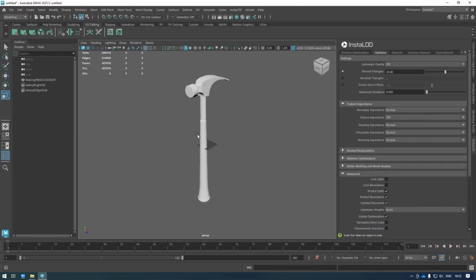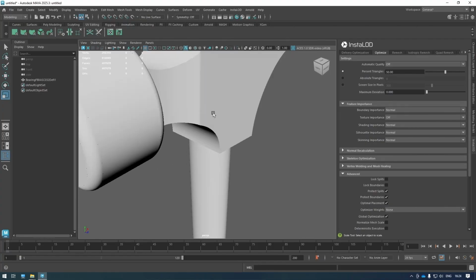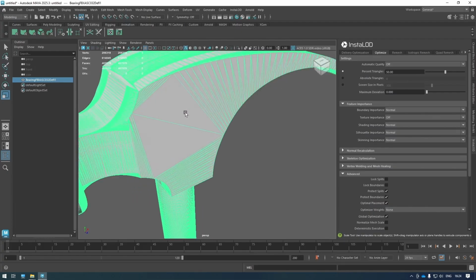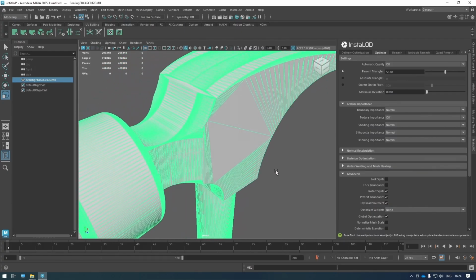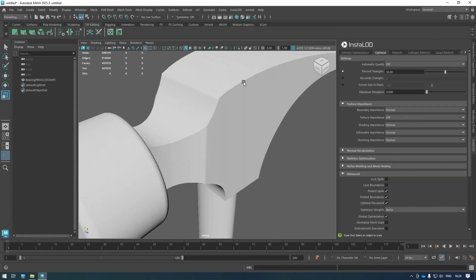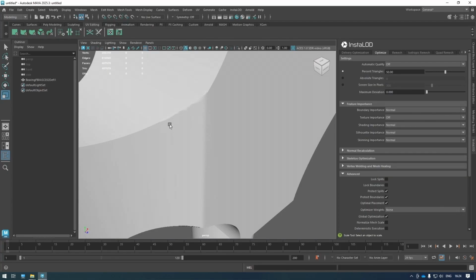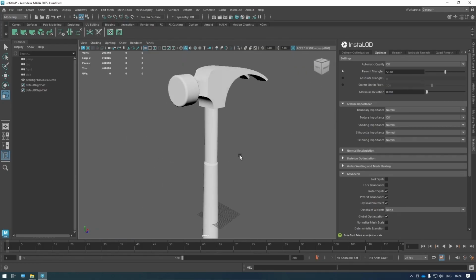So for this next example, we're going to look at this hammer, and this CAD data, if something could have gone wrong with the tessellation, it did. And if we look at it, one of the things to note first is that we have some gaps here in between the patches. And we also have some bad normals here as well.